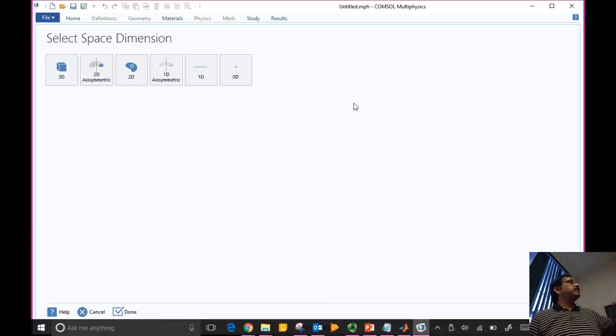Once I pick the wizard, it tells me that I can solve a 3D problem, a 2D axisymmetric problem, a 2D problem, a 1D axisymmetric problem, a 1D problem, and a 0D problem. Okay, so we need to develop in this course what these mean. Where do these models come from? Okay, so the D here, the space dimension, as it says, select the space dimension, stands for in how many spatial dimensions a particular dependent variable changes.